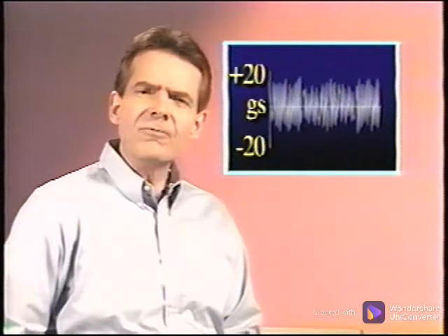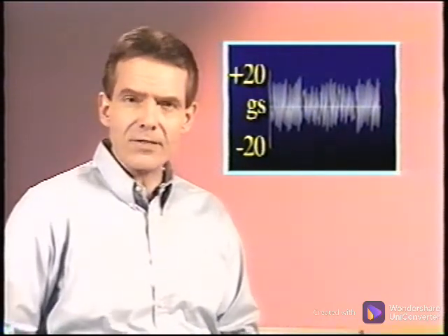Gear wear shows up as side banding around the gear mesh frequency and excites the natural or resonant frequencies of the gear. This natural frequency usually has side bands spaced at shaft speed. Sometimes the gears could be so worn that they appear as looseness in the spectral data. The waveform may have a high level of impacting and can exceed 20 to 30 Gs.